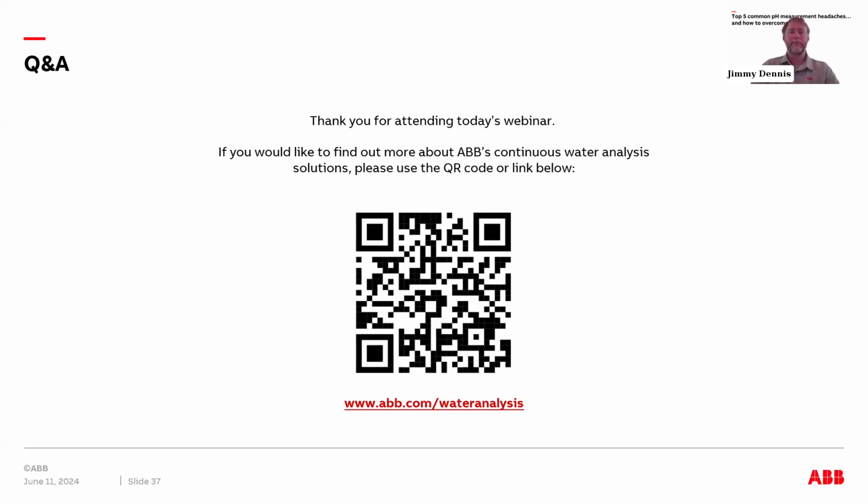Okay, so we've got some long ones in here. There's one from Steve. This is going to be one for you, Nick, right? Yeah, I can summarize quickly. So Steven mentioned he has 2 points of contact in the process. They match on the lab reading. When they're out of the process, they read correctly. But as soon as you put it in the process, there's a deviation. And typically they do a 3-point cal. So that's the tricky part.